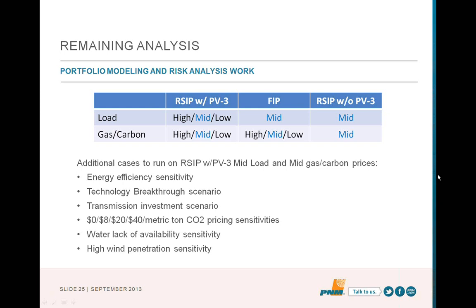Okay, so the question is trying to reconcile the current recommendation to what the findings were in the IRP 3 years ago. One of the things to keep in mind is that in the IRP 3 years ago, this revised state plan wasn't something that was contemplated. Basically, what we're looking at is a combination of shutting down units and installing SNCR, a much less capital-intensive technology. What was looked at in the previous IRP was shutting down units or installing SCR. So one of the things that bridges that gap, where shutting down the capacity at the coal plant and replacing it with something else looks economic now, whereas it didn't 3 years ago, is because we're saving capital dollars on the NOx reducing pollution control.